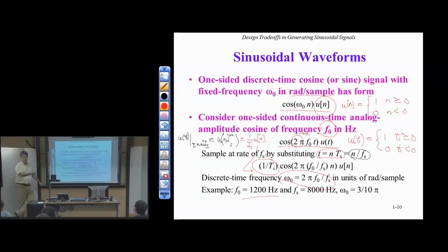It's a staircase approximation. It's a rectangular pulse, if you will, or pulse train, which is great if you want to generate a rectangular pulse train. This is exactly a good way to do it. If you want to generate a cosine, then you want to use the scaling to your advantage. So what kind of scaling value could you use before you did the typecasting?